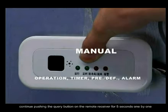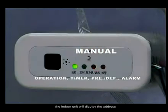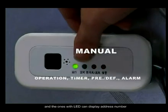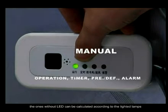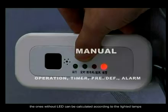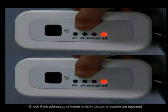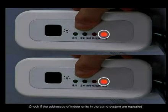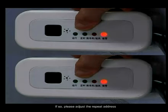Continue pushing the query button on the remote receiver for 5 seconds, one by one. The indoor unit will display the address, and the ones with LED can display the address number. The ones without LED can be calculated according to the lighted lamps. The address code table is as follows. Check if the addresses of the indoor units in the same system are repeated. If so, please adjust the repeated address.